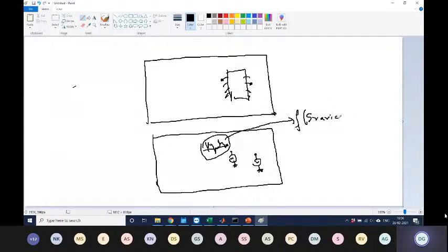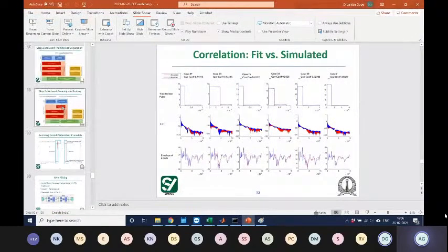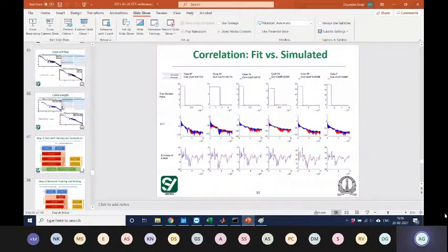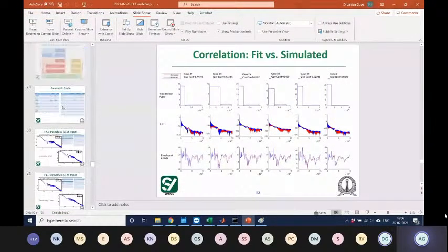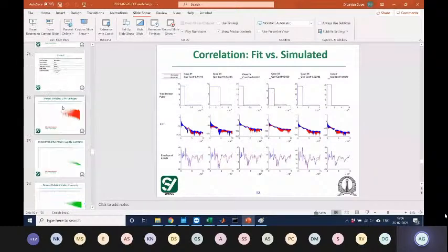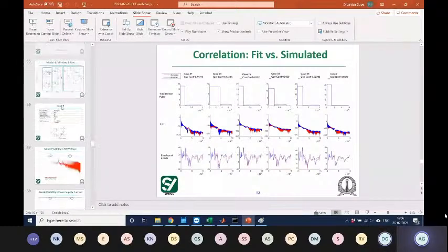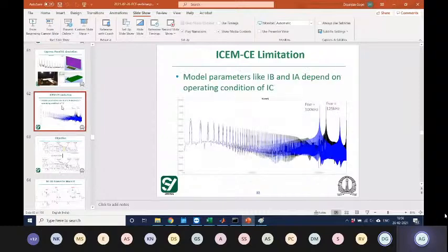Very good. Okay. So then my question was the frequency domain responses you showed, they all had some basic structure. They were all periodic, with some spikes at intervals that slightly changed. They get more compressed and so on. Can you explain the reason for this kind of structure? Is it something natural? Yeah, it's because of the periodicity of the waveform. The switching is happening very periodically, and that's why the structure is there.